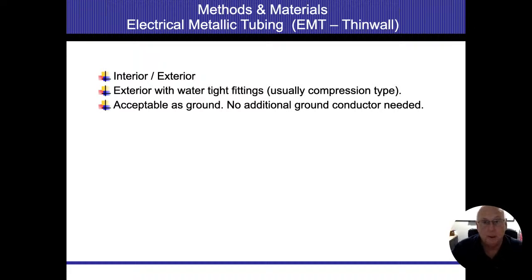Now there is a push for this to have ground wires installed with conduit. And the reasoning behind this is, and I'm sure we've all seen it, if that conduit comes loose, I just broke my ground for everything downstream of that. So if this is my line side and this is my load side, and on the load side I had a wire come loose and energize my conduit. If my conduit is disconnected, I don't have a pathway to get back to my panel, to my bond screw, to my neutral, which allows that free flow of electricity and trips the breaker. I got nothing. All I'm going to do is energize that conduit, and everything else attached to that conduit is going to be energized as well.